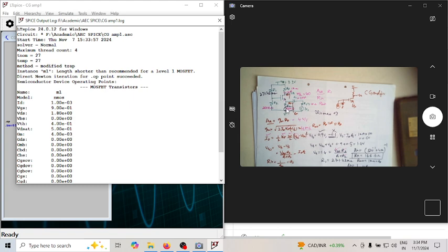Of course, you can see this VD is also the voltage at this point. And how much is VDS? It is 0.5 dropped here, and here it is 1 volt drop. 3.3 minus 1.5 is 1.8 volt. Can you see this is 1.8 volt? This is VDS, which is 3 volt minus 1 volt minus 0.5. So 3 minus 1.5 is 1.8. Sorry, 3.3 minus 1.5 is 1.8 volts.